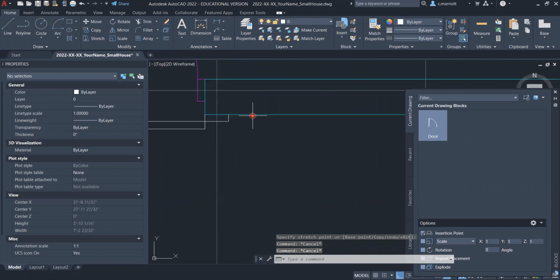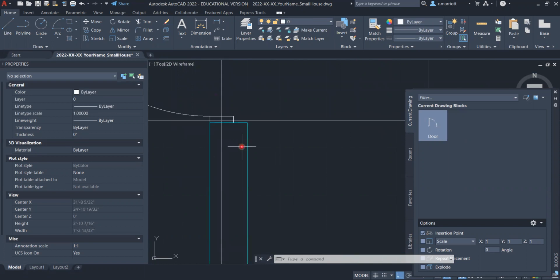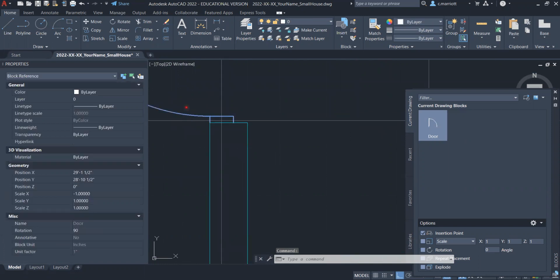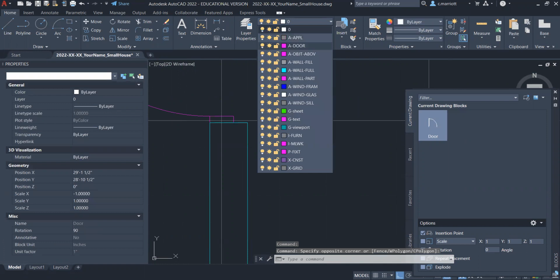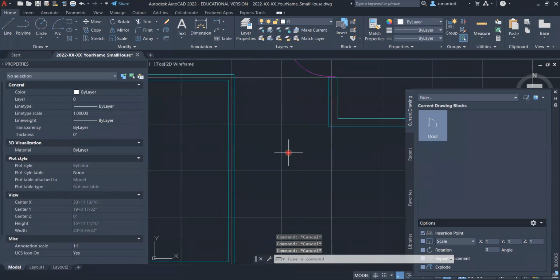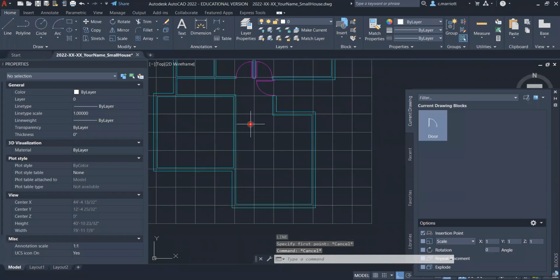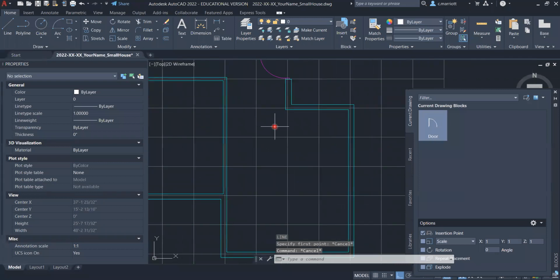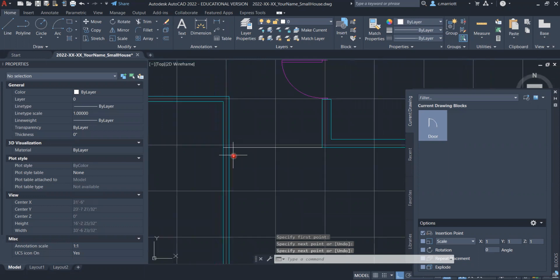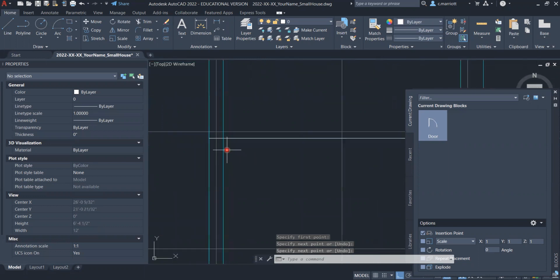You want to look for those cyan lines pulling all the way through on all of your doors. This one, let's move that to the lead door. All right. I think I'm also going to make my living room and dining room open up to one another. So I'm going to need a little line for this wall to stop. Use the trim command.